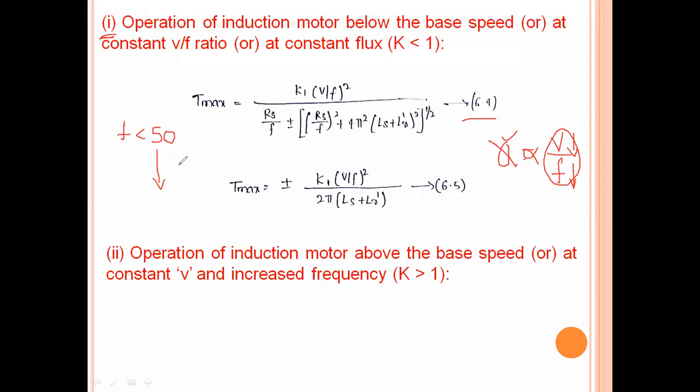And if the flux is increased beyond its rated value, then because of the saturation, the torque capability of the motor will also get degraded, which means the performance of the induction motor will be completely degraded.